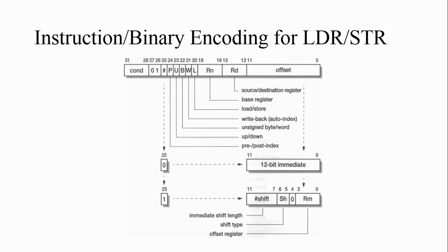So you should convert this instruction into a code known as the operation code, which in the case of ARM will contain 32-bit binary numbers. Whatever instruction you write will be converted into a 32-bit opcode. How the instruction is converted from the actual instruction to the opcode is explained by the binary encoding, or instruction encoding, of that particular instruction. So for the LDR or STR instruction, the binary encoding will be done like this.